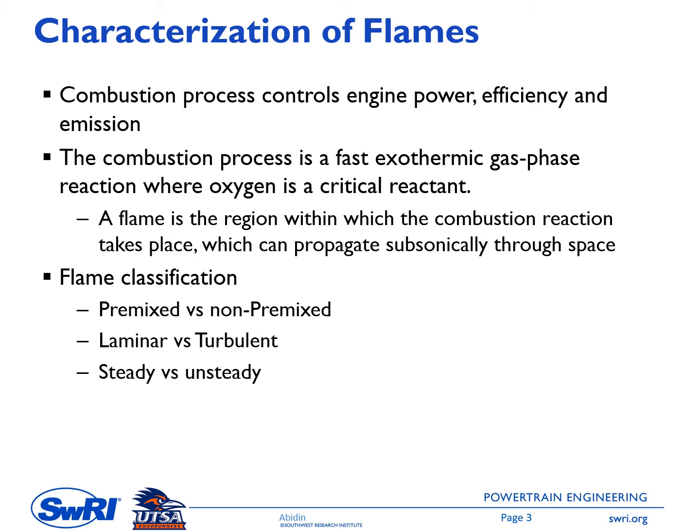Then the auto-ignition or self-ignition of a portion of the developing mixture of already injected and vaporized fuel with the hot air starts the combustion process. And this will spread rapidly. The burning process proceeds as the fuel and air mix to the appropriate composition, so it should be within a certain range from the stoichiometric mixture composition.